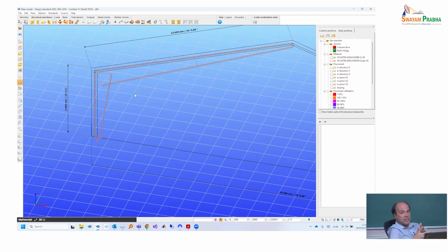As we saw in Consteel, if you want to perform buckling calculation, which hopefully you want, then the only way in Consteel to get there is to perform linear buckling calculation, but linear buckling calculation is really a 3D problem. Even if this is just a 2D structure, the displacement will go in the weakest direction of the structure, which is always out of plane. So we need to also assign out of plane supports.